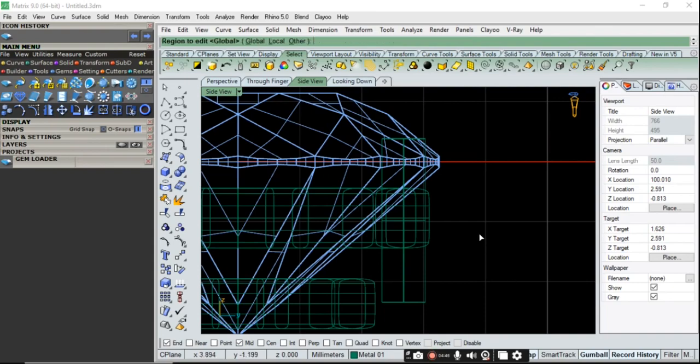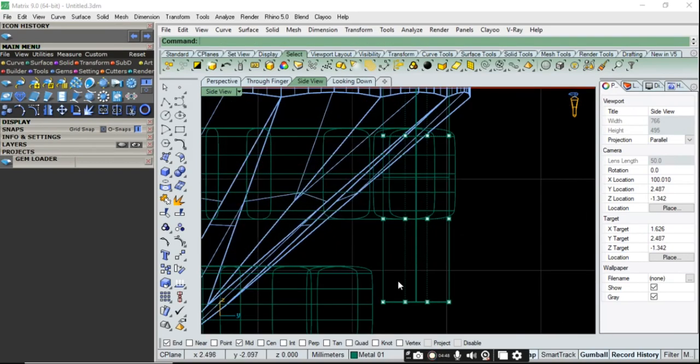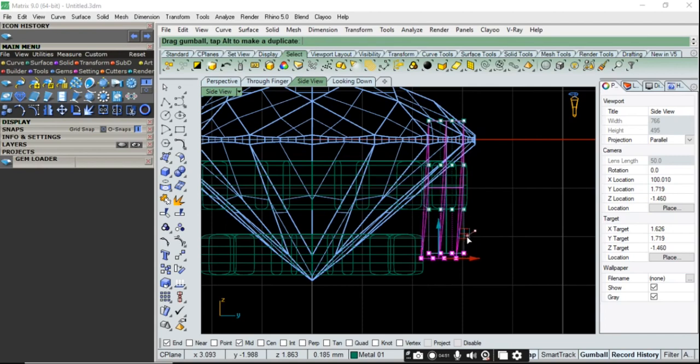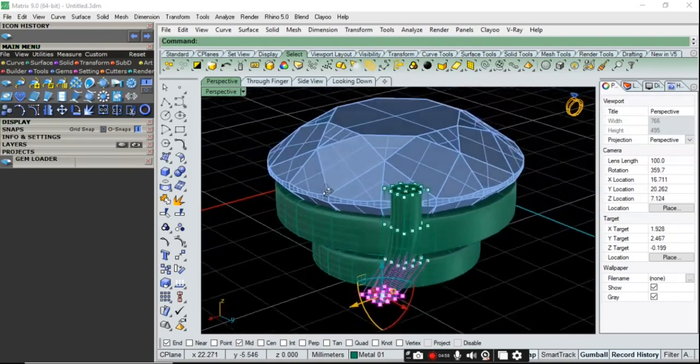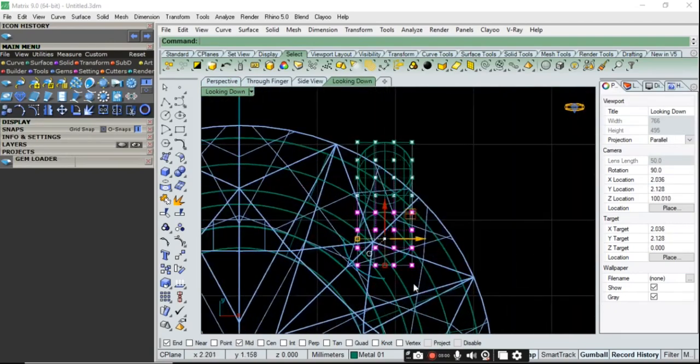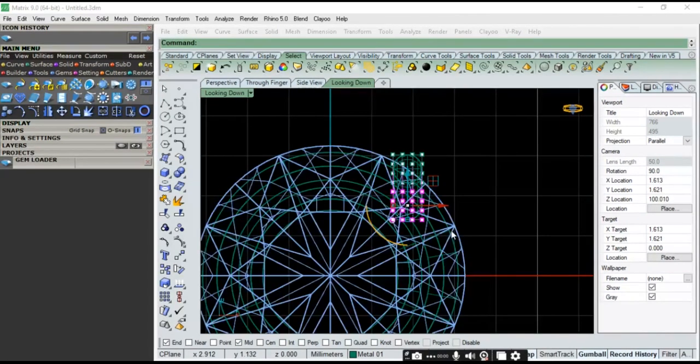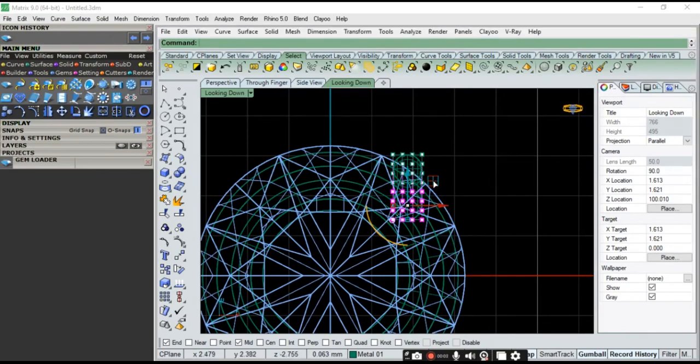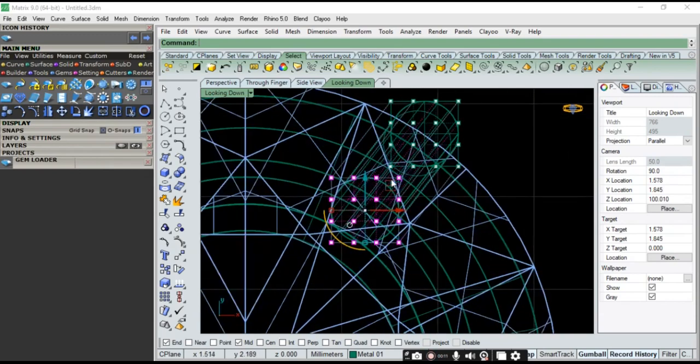Now to create cage, we apply cage edit option. By applying cage edit, it will create a cage of control points. So if the cage is okay, then set groups of points as per our requirement. You can see in the video I have just selected the bottom 4 points and adjusting them to set prong position as shown in basket head.